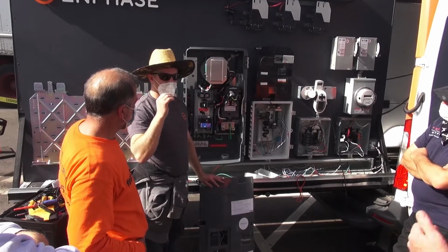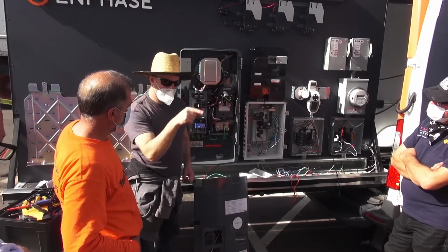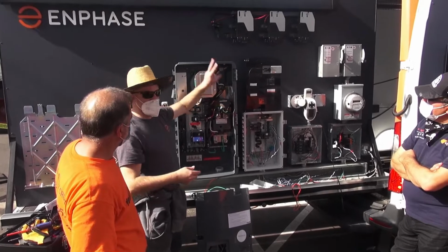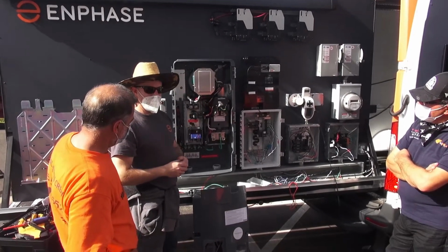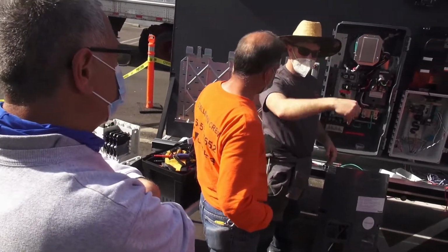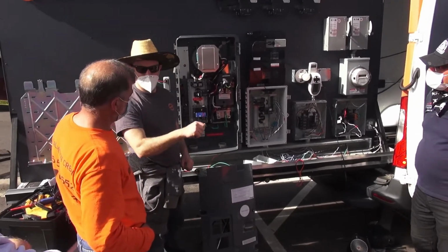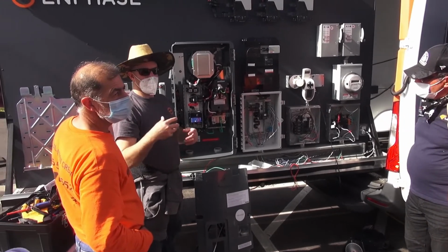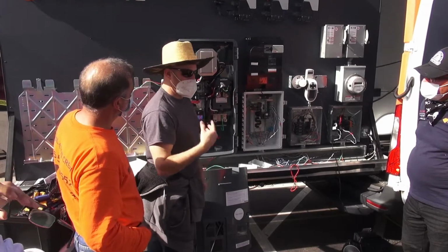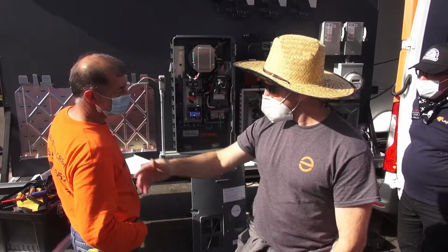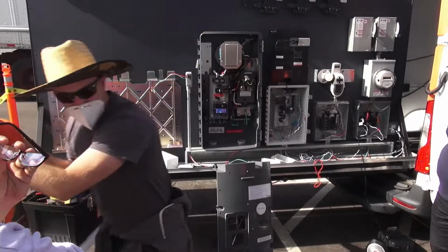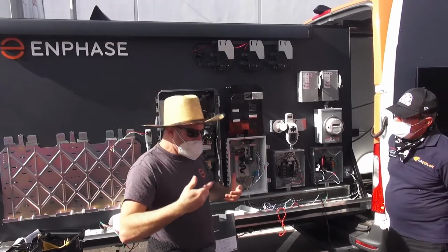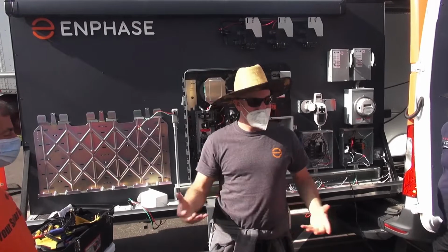So does that make sense? Something that's grid forming has to be able to be told, hey, turn off. Let's go to a safe mode. Otherwise, they'll just send out 240 volts all day long. And you're like, oh, wait, there's an emergency, please turn off. That's what you're doing with that switch, is telling them. Whereas in all of the old ones, as soon as you turned off the disconnect or the breaker, rapid shutdown. Those old ones, what they're doing, they're kind of like following the leader, right? You're in front of me, I follow you. If he stops, I stop, right? The grid went away, I shut off immediately. These have the ability to keep on going, even if that other stuff disappears.